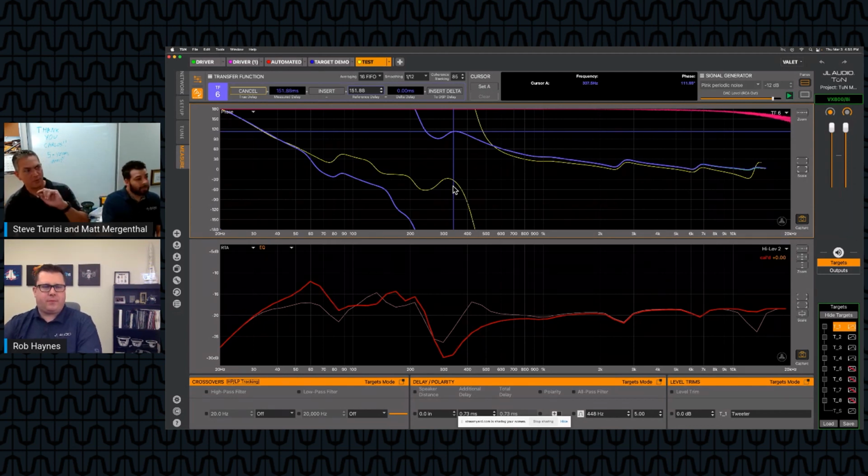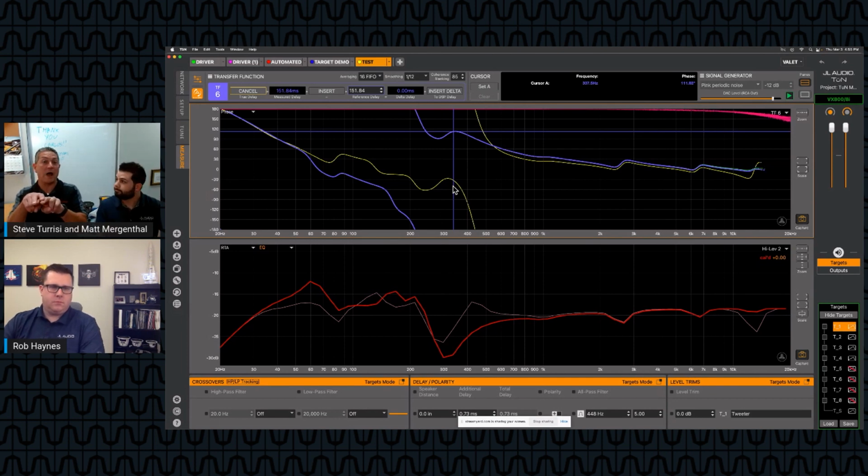Think about what would happen if we took the left and right signals, summed them together, and saw what would happen. We would say, there must be an all-pass on that. And we put in an all-pass. We wouldn't know what frequency necessarily. We kind of see where the dip is, so we put it at that frequency. And what we would see is suddenly at that frequency, it'd be good. But at the other frequency, it wouldn't be, because you didn't know there was another one on the other channel. You're only seeing the result of both of them together. So you're kind of chasing your tail a little bit.